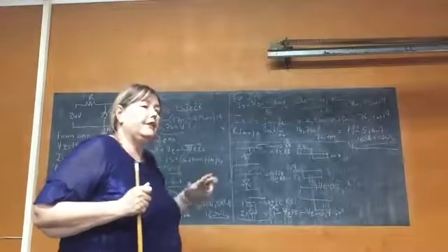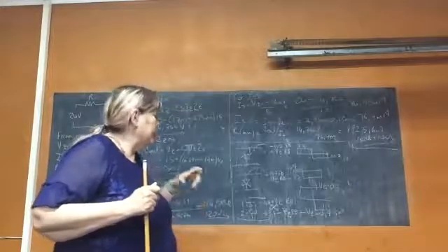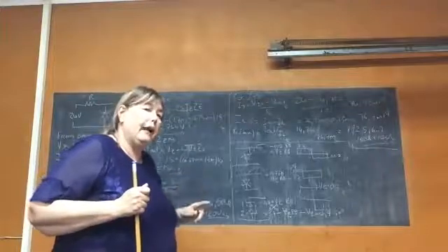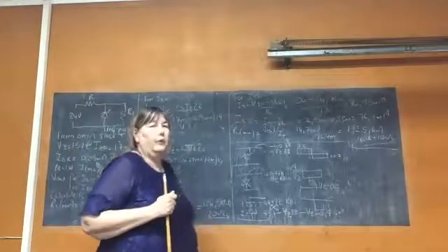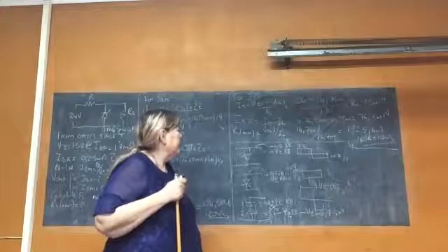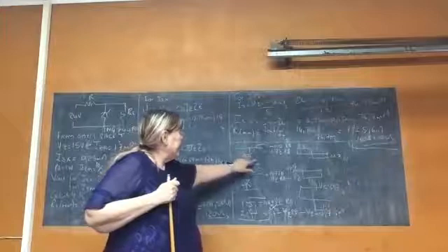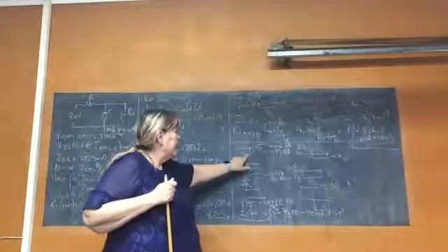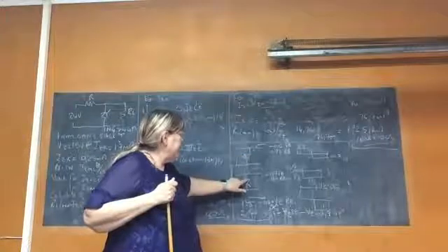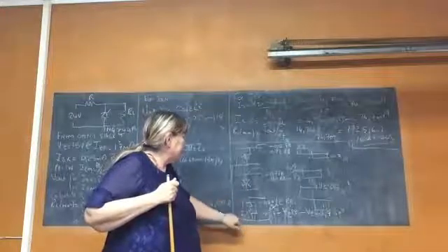Because the forward and reverse bias is different than a diode. That is where normally everybody goes wrong. The forward bias part is exactly the same as a diode. Therefore, I start with the forward bias part. If my Zener diode is forward biased, I see the anode plus 0.7. This one plus 0.7.